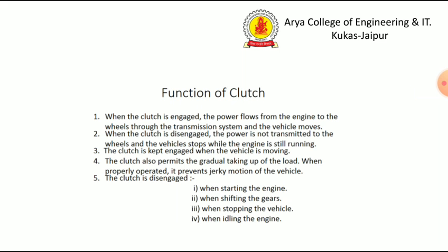The functions of a clutch. The basic functions of a clutch are: when the clutch is engaged, the power flows from the engine to the wheels through the transmission system and the vehicle moves. And when the clutch is disengaged, the power is not transmitted to the wheels and the wheels stop while the engine is still running. The clutch is kept engaged when the vehicle is moving. The clutch also permits the gradual taking up of the load. When properly operated, it prevents jerk motions of the vehicle.